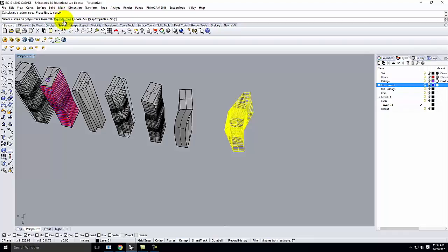Generally speaking, you want it to be exploded to pieces, yes, because if you don't explode it into pieces, there will be surfaces that overlap on each other, and you'll have to do it manually afterwards. So you might as well just say explode. The next thing is labels set to yes or no. I like to turn labels set to yes, because otherwise figuring out where the various pieces go is a really big challenge, and what unrolled where. So we're going to turn labels on. So we have explode yes, labels yes, and then keep properties we'll set to no.